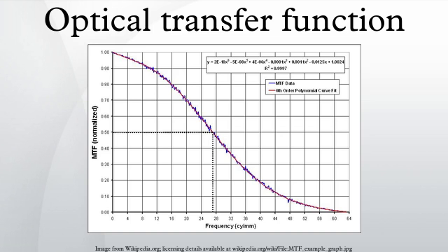A higher number of pixels on the same sensor size will not allow the resolution of finer detail. On the other hand, when the pixel spacing is larger than 1 micrometer, the resolution will be limited by the separation between pixels. Moreover, aliasing may lead to a further reduction of the image fidelity.